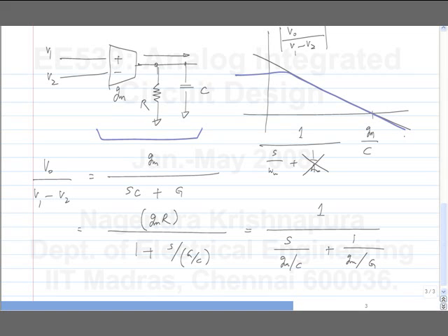And what would make it do this? Huh? The input? The input pole. So essentially, if Gm itself has a frequency dependence, okay, between the input and output, you will have something of the sort. If there is some frequency dependence inside the transconductor. Okay. So in fact, you can make it without this also. We'll see. Right. So it is possible to have something like this, predominantly a first order response. But most of the good op amps that we will design will have some poles inside the Gm, and because of that you will have something of this sort.